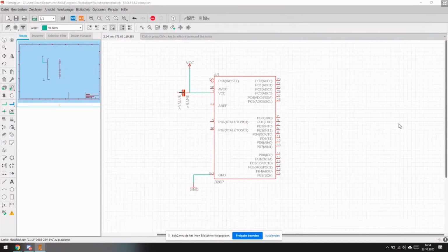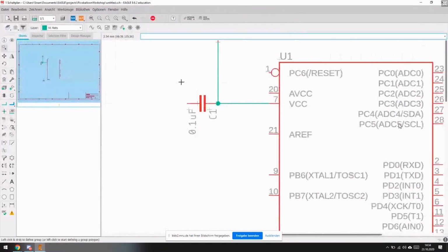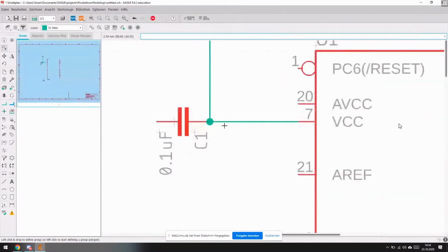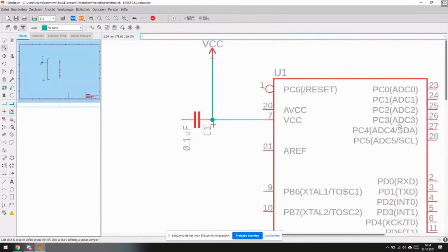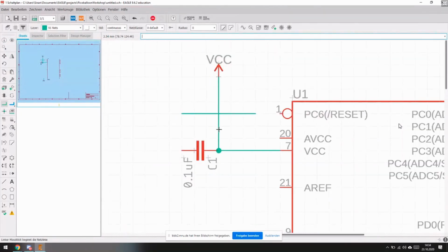Okay, we'll place the first one here. Just like that. Now we have our component here. It's connected to here, and as you can see, here's a little dot, and that dot just means that traces are connected. If I just draw a net right here, you can see these are not connected. It looks like they're connected, but on schematics, these are not. These are connected when you do a junction. The junction tool is right below the net tool.